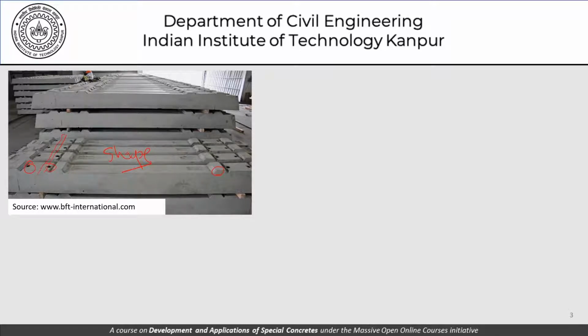Apart from that, what is the kind of material that we use? What is the kind of loads that we consider? The loads that we have to consider are not only the loads which the sleeper is under when it's in service, but also the loads while it is being handled in the plant. So you can imagine that the sleepers were surely not cast the way it is shown. We'll show you some pictures. From that position to this position, what were the loads that acted upon during handling? What was the age of the sleeper at that time?